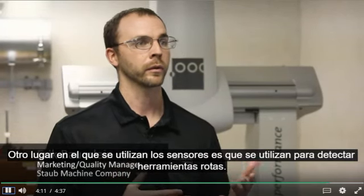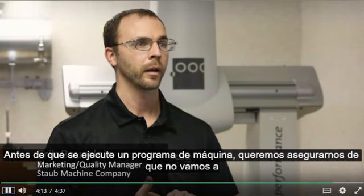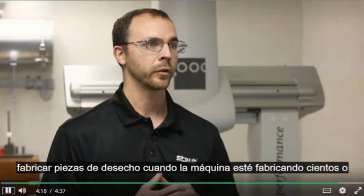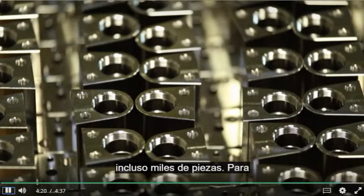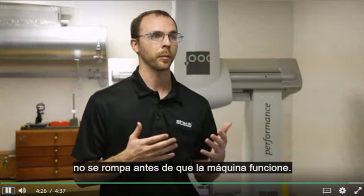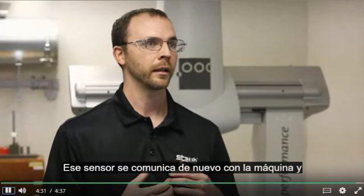Another place that sensors are used is to detect broken tools. Before a machine program runs, we want to make sure that we're not going to be making scrap parts when the machine may be making hundreds or even thousands of parts. So that sensor will check to make sure that a tool is present and not broken before the machine will even run. That sensor communicates back to the machine and kind of qualifies the run for us.